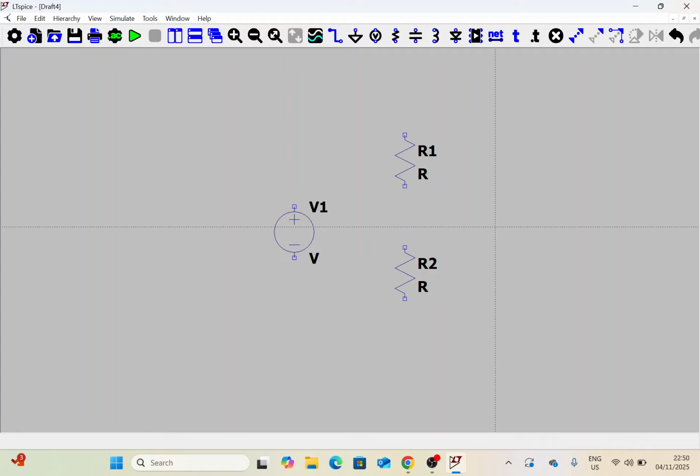The next thing I want to do is to just connect the wires. So I press W on my keyboard. I get to the point where I want to bend. I want to bend again, and now I'm going to go straight through all of them like this. Come here and come all the way here. I've made this circuit unnecessarily huge, but we are learning, right? So I'm going to place my ground here, so that becomes the reference point for measuring the voltages and the current during the simulation. The next thing I want to do is to take my output from here.